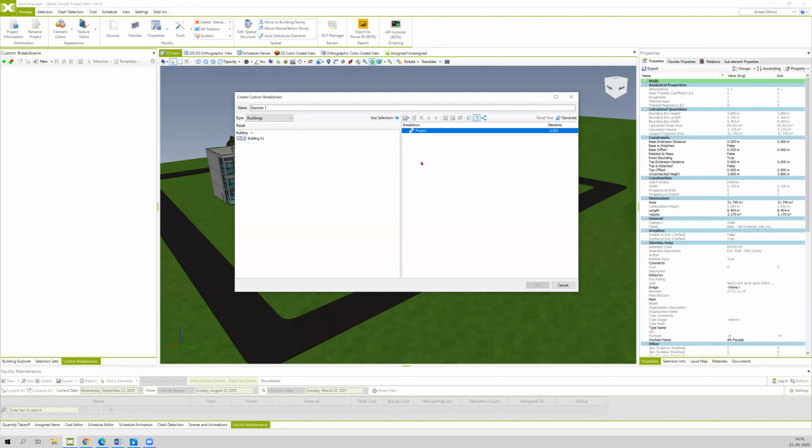So now we will go back to the command which is named Add Breakdown Rule and click on it. And here in the drop-down menu, you can see various options. And in this exercise, we will choose the Group by Source option. And to finish the process, we will click on the OK button.